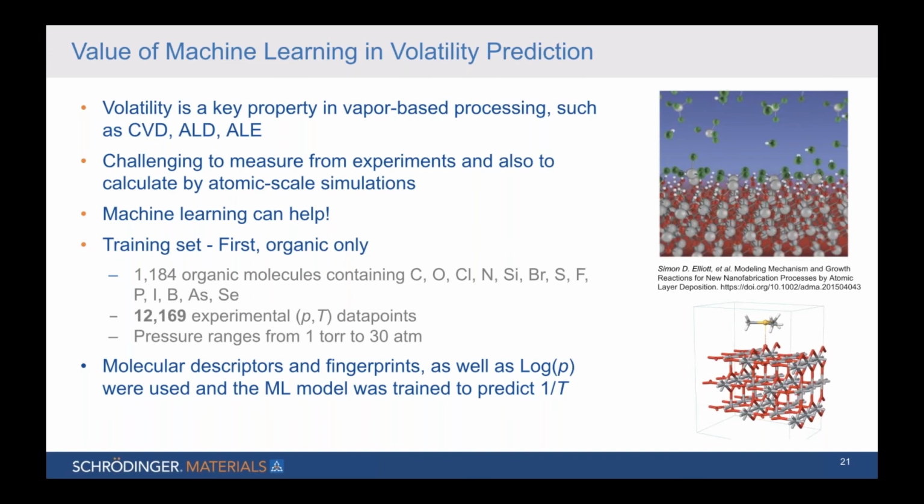A key factor in this process is being able to selectively allow the wanted precursor compounds to vaporize and be continuously drawn into the deposition chamber, while the unwanted volatile components can be removed by reduced pressure or inert gas purge.